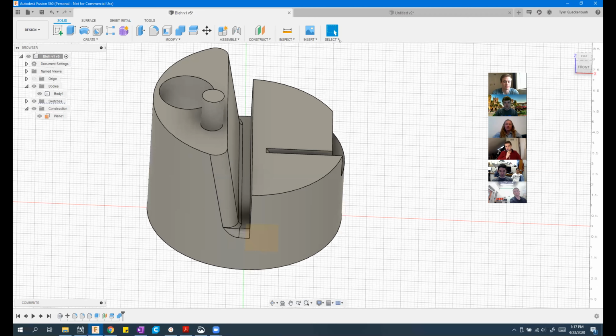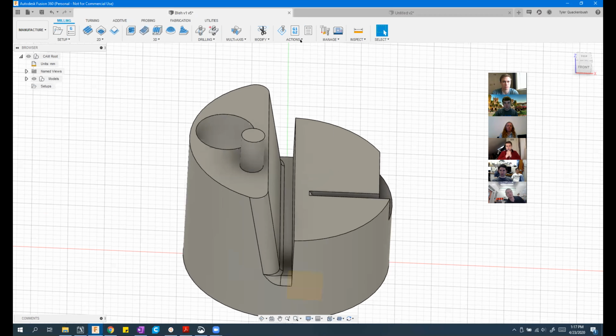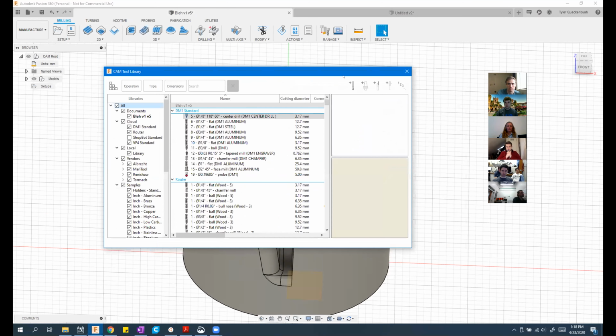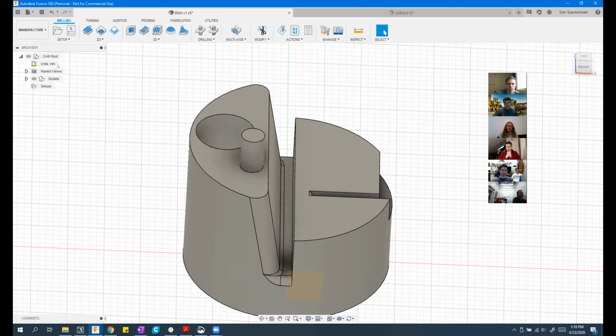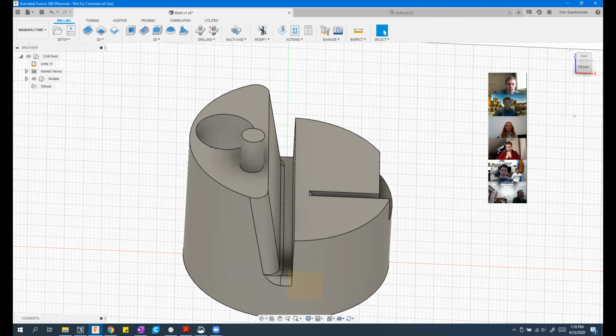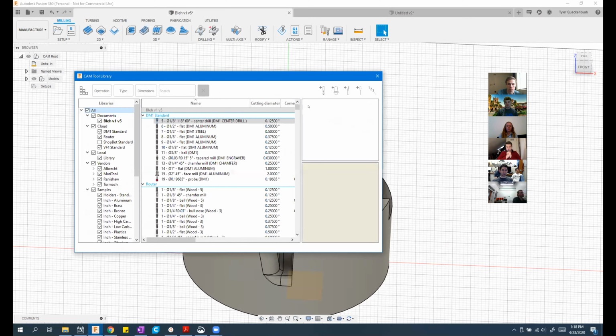I can try. All right, go for it. Okay, so you have the tools that you physically have, let's say the tools we physically have in the shop. You have the dimensions and what kind of material, what's holding it, all in that list. And then you can call on that list when you're camming, so the right tool is used at the right time. So then the machine can follow that, call that tool, and use it. Nice. Perfect, Lizzie. Any addendums to that?